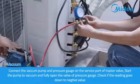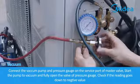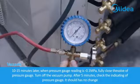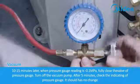Start the pump to vacuum and fully open the valve of pressure gauge. Check if the reading goes down to negative value. 10 to 15 minutes later, when pressure gauge reading is minus 0.1 megapascals, fully close the valve of pressure gauge.